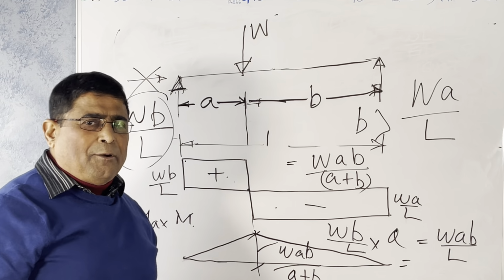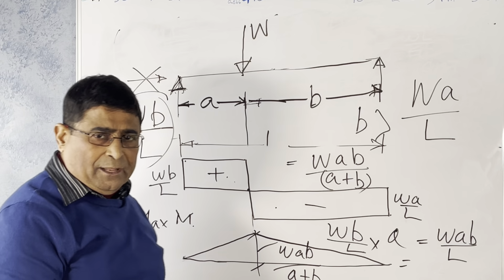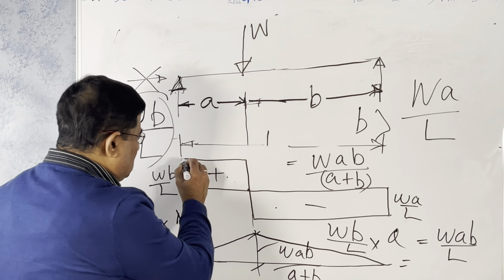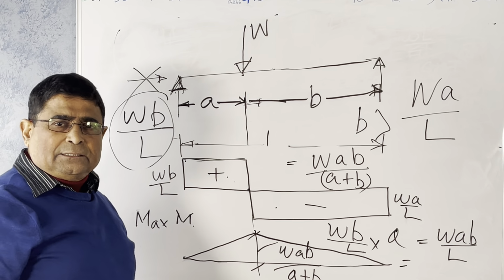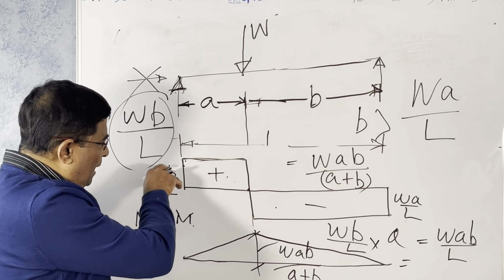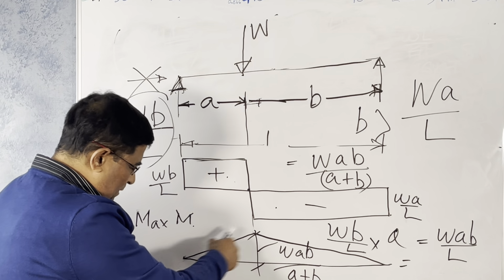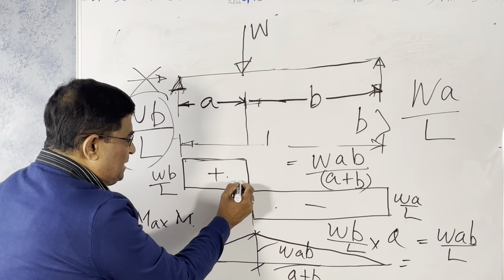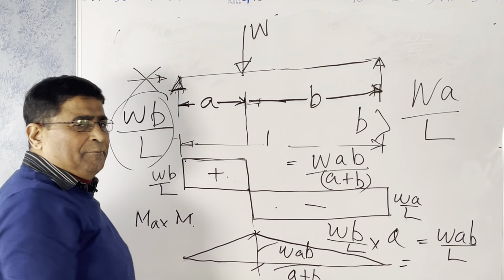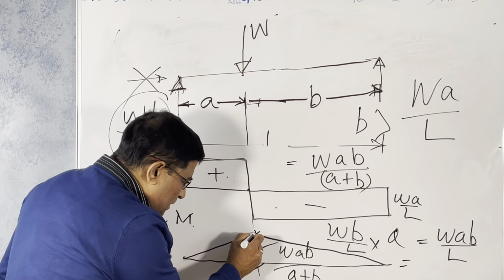This is simple. Bending moment and shear force diagram is simple. By looking at it directly, you can say what the value is. Consider the load: the shear force is constant until the next load comes in. The moment is linear, and wherever the shear force diagram changes its sign from positive to negative, that is the place where you get the maximum moment.